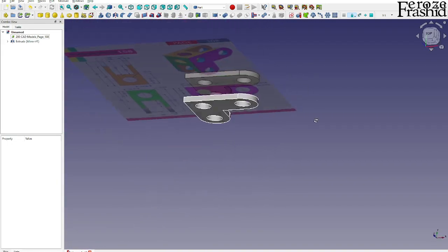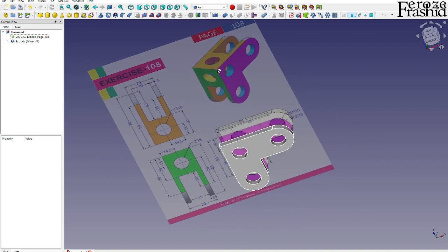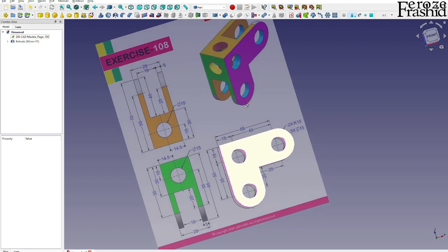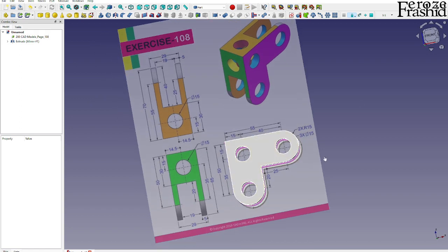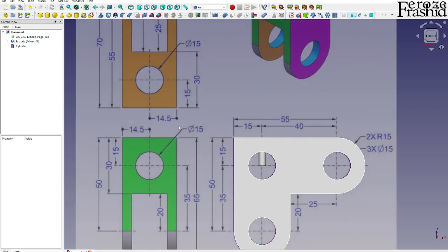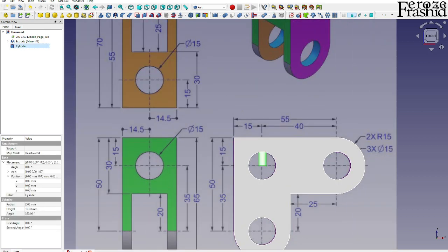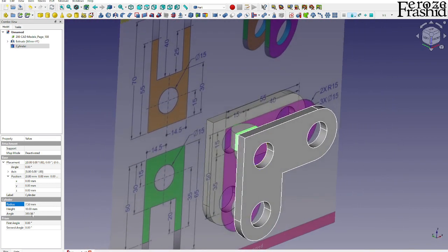Okay, so now we'll have to make a cube that will have 3 holes. So we'll build on these 3 cylinders. First thing first, I'm gonna go ahead and bring in a cylinder right there and make it radius 7.5, which is 15 millimeter in diameter. And I want to say height would be more than definitely 30. So let's go ahead and make it 35.